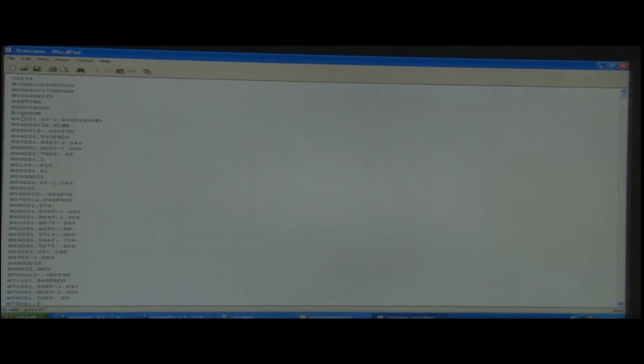So, there are certain conditions in which the program is written by the software. It has its intelligence and also certain limitations. Those sometimes have to be taken care of for specific machines. The operator might have to put in their own values to keep the reference at the proper alignment, or maybe some other tool value to select the tool.